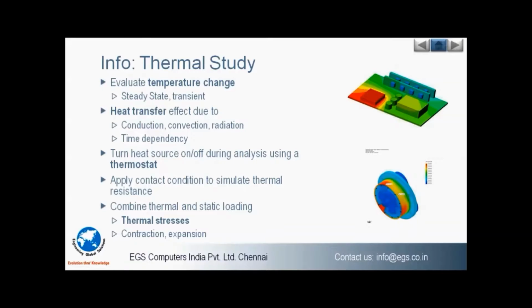For the heat source or the thermostat condition, we can directly switch on and off during the analysis based on the real-time conditions. And using this, we can also apply certain boundary conditions or contact conditions for the designs. By this, we can evaluate the thermal stresses, either a contraction or an expansion for the thermal studies.